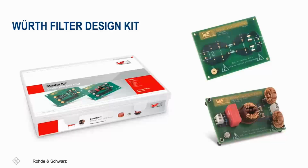Wurth Electronics also offers a specialized filter design kit. They are a wonderful resource for testing the effectiveness of various filters. This kit includes X and Y capacitors, as well as common mode chokes of different sizes and material to tackle different frequency responses. It enables us to easily swap out components and determine which filter works best. Another reason why we did the experiment with capacitors is that the filter board typically requires soldering components in place, making it more convenient to use sockets for capacitors, but for the common mode chokes, it will be much more difficult.